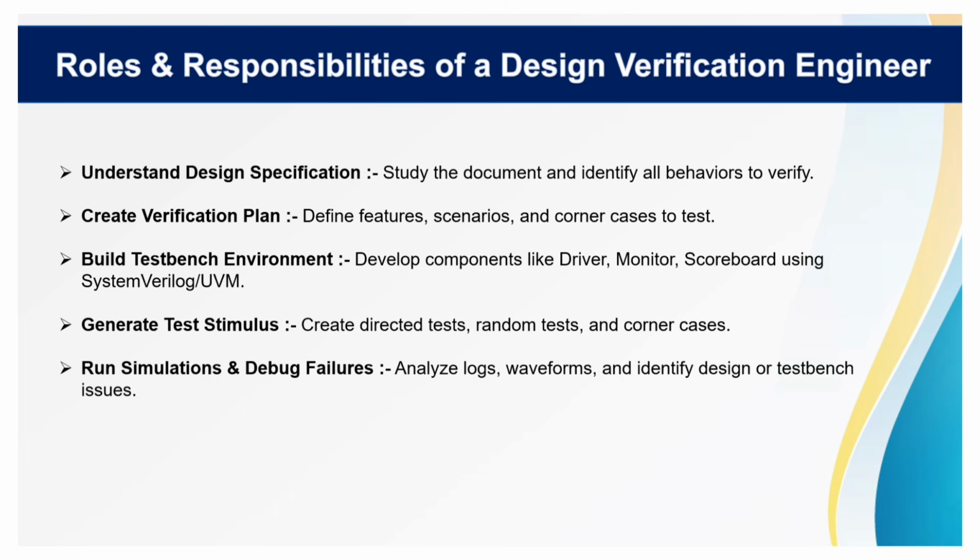Next comes running simulation and debugging failures. If something goes wrong during simulation, the DV engineer carefully analyzes logs and waveforms to understand the issue and determine whether the problem is in the design, the test bench, or sometimes even in the specification itself.